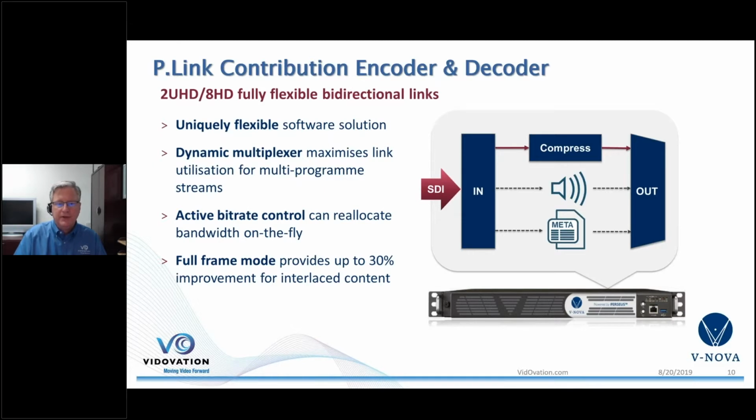If you're home running all your cameras to master control, really the camera that's hot, that's being broadcast, is the only one that needs the maximum bit rate. If a camera's on standby and a director hasn't taken it, but I have a slide that'll get into that. And you can control the bit rate adaptively, and that dovetails into this REMI at-home type workflow.